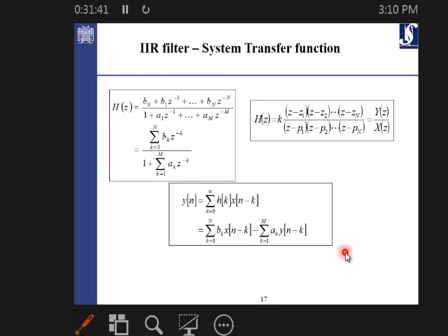So if you need a system to be like ARMA systems, autoregressive and moving average altogether, or a system which contains both zeros and poles. So the transfer function of a system, if you want to have such a transfer function which contains both zeros and poles, like here. This is a filter containing zeros and poles, like this. So these are different types of representations of a filter.